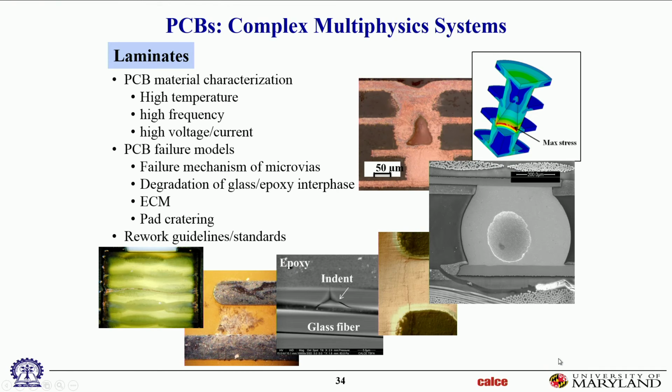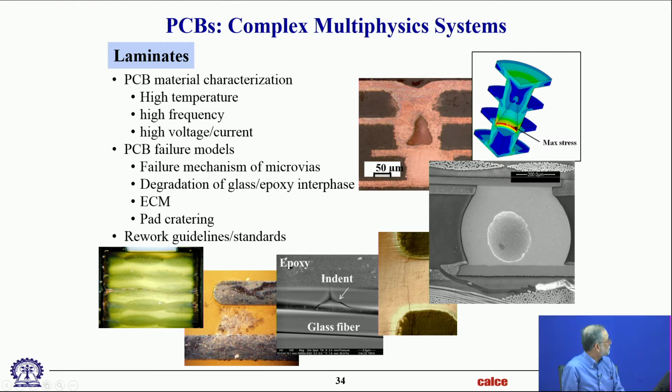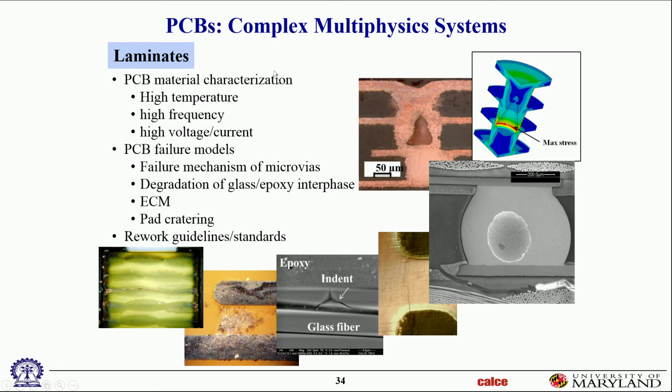So that was for components: active components, passive components. Now let's talk about the interconnections and the circuit cards. Again, I'll go through more details later on, but just an overview. Here are metal traces on a circuit card. You can see there's dendrite growth on the surface of the circuit card, across the metal traces, causing shorts.